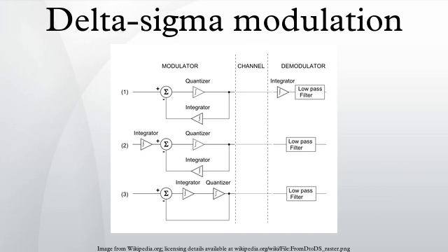On the other hand, delta modulation shapes both noise and signal equally. Additionally, the quantizer used in DM has a small output representing a small step up and down the quantized approximation of the input, while the quantizer used in SDM must take values outside of the range of the input signal, as shown in Fig A3.